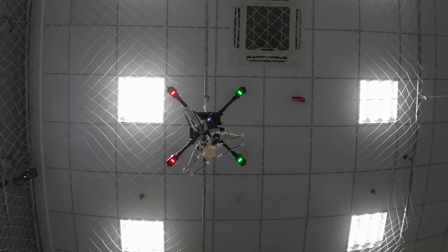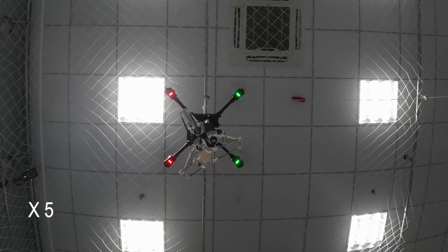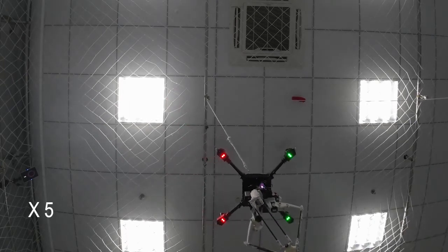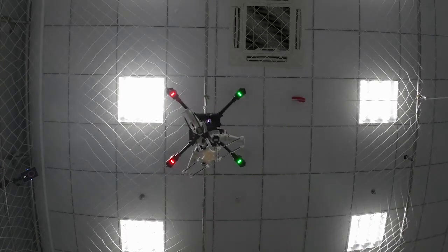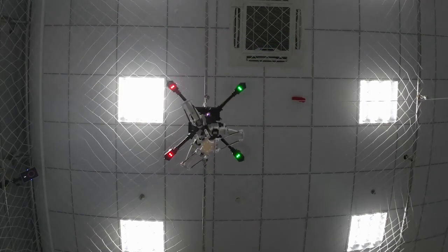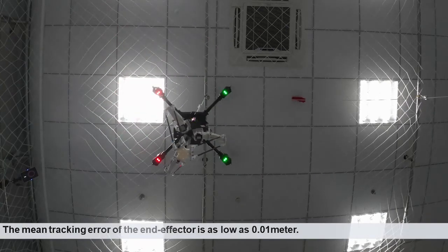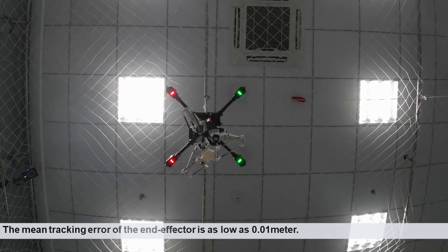The purpose of this experiment is to validate the EP mode of the proposed cooperative planner together with the flight controller. The control objective in the third experiment is that the end-effector can accurately track a desired complex trajectory. Different from the second example, this example does not require to specify the desired trajectory of the quadcopter base. The mean tracking error of the end-effector is as low as 0.01 meter.